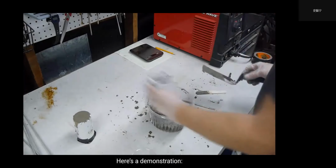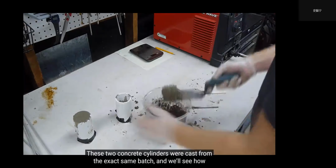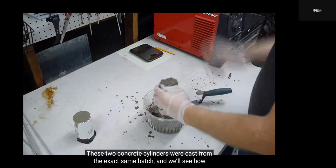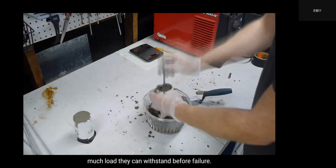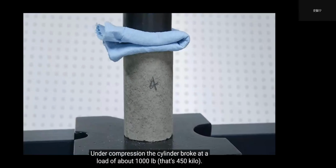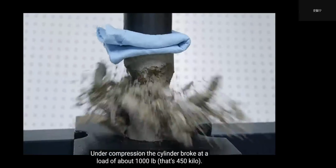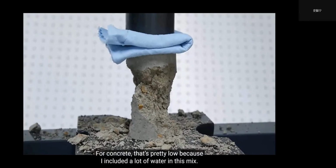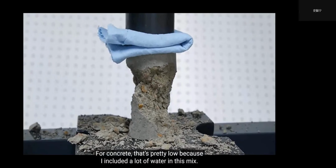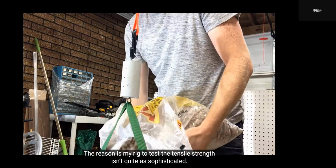Here's a demonstration. These 2 concrete cylinders were cast from the exact same batch, and we'll see just how much load they can withstand before failure. First, the compressive test. Under compression, the cylinder broke at a load of about 1,000 pounds. That's 450 kilos. For concrete, that's pretty low because I included a lot of water in this mix. The reason is my rig to test tensile strength isn't quite as sophisticated.